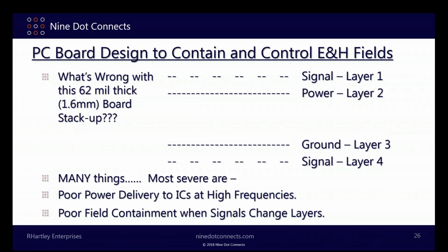If power and ground are in the middle of the board, how are you going to move those fields? Well, the answer most people give is the energy will move through the decoupling cap. And if your circuit board, if you're lucky enough to have rise times that are in the 2, 3, 4, 5 nanosecond range, yes, you can get away with this.